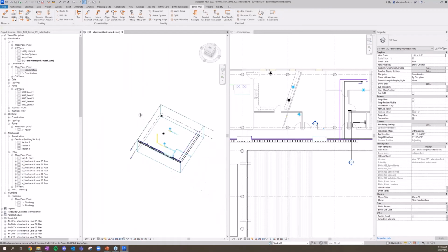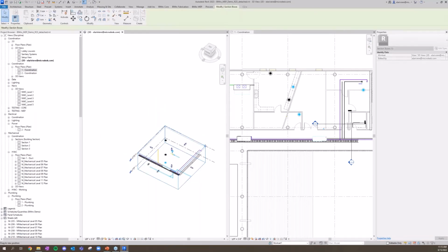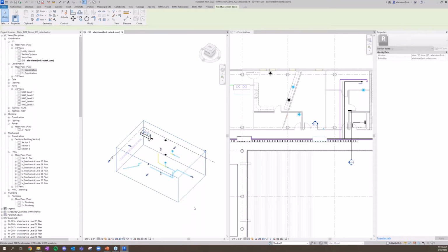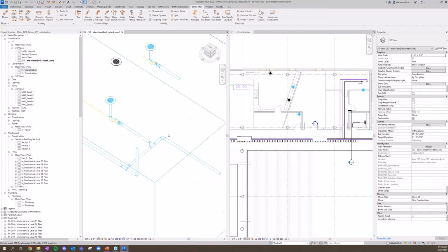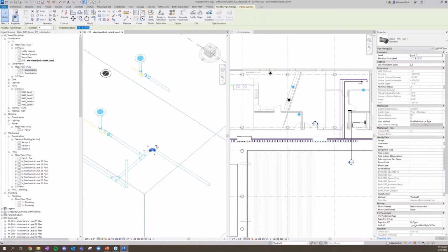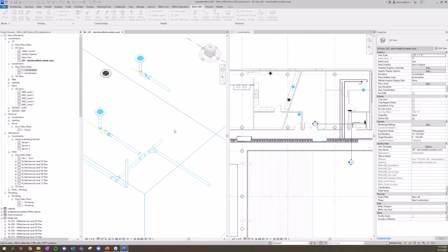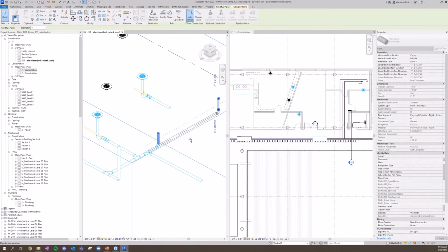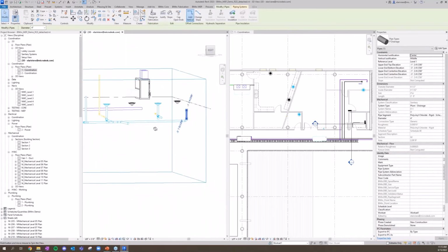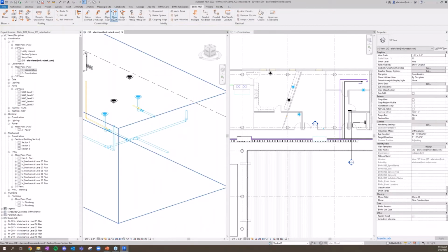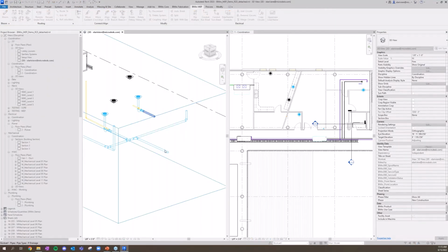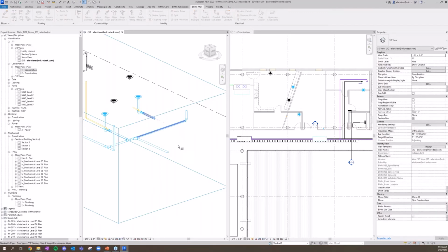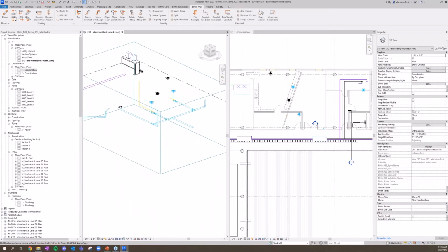Now this is where you're really going to notice these alignment and move connects coming in handy. Anytime we're dealing with slope pipe, stuff gets a little messy, things don't like to connect. We just tried to make that easy. We want everything to connect as smoothly as possible. So jumping down here, I can just start blooming my elements out. It's going to maintain any of those slopes I've already created. I can give myself extensions and just move those extensions on, because 3D views allow us to do that. You can then look over here and notice these aren't aligned. Well, that's exactly why align branch exists. It allows me to drop that down to the exact height and then use trim extend to bring those elements together. Very, very quick.